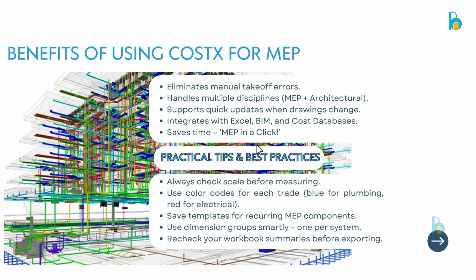The next is to use dimension groups smartly. You can use one per system, then recheck your workbook summaries before reporting. Also recheck the quantities you import to your workbook before you export them out to Excel.